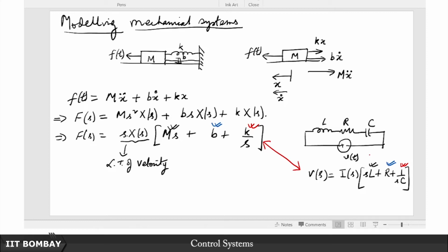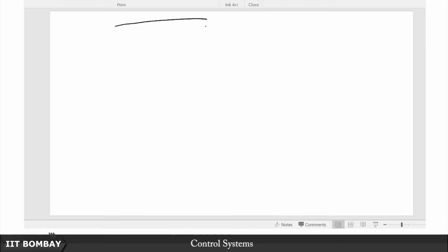So we shall now see how connecting the analogy between the electrical circuit and the mechanical system will aid us in being able to write the equations for the mechanical system without always having to draw the free body diagram. Recall that when we were dealing with electrical systems, we did not always write individual mesh equations or node equations by carefully calculating everything. We often did it by observation, as I might have remarked in a previous lecture. Now we are suggesting that the same thing can be done for a mechanical system if you understand what the analogy with the electrical circuit is like. So let us quickly take a look at one such example, and things will hopefully be a lot clearer. So consider a mass, a box such as this.